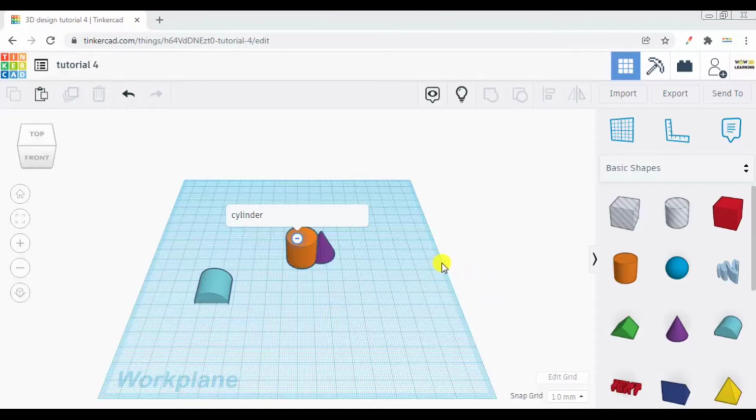So now you also have to remember that once you have placed a note on an object, if you want to hide it, make it invisible, you can control this by using this toggle notes visibility icon, or you can use the keyboard shortcut Shift+N. If you press it, it is hidden. If you press it again, it will be visible. So like this you can play around.